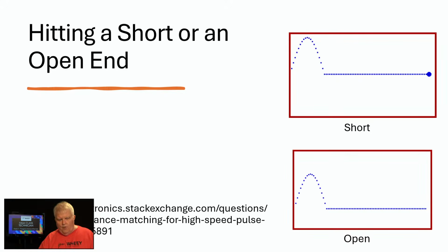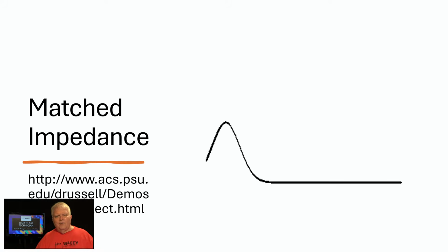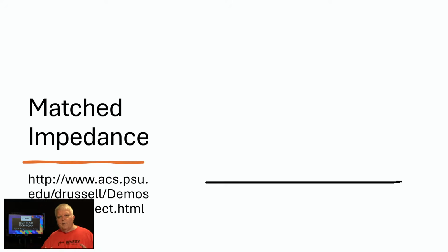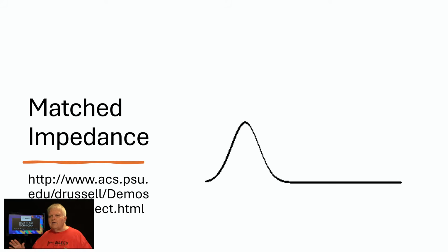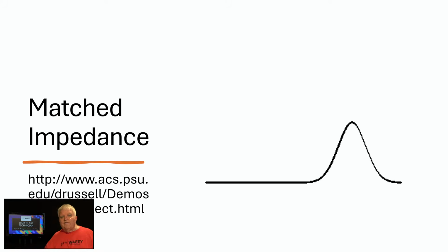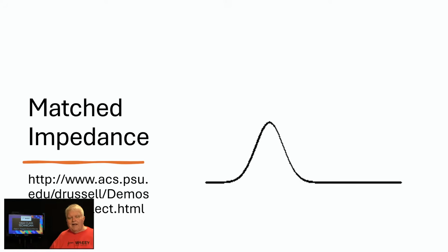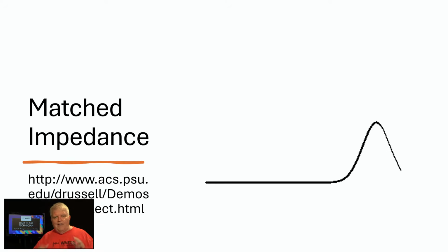What we're looking for, though, is this, where the energy leaves the transmitter, goes down the transmission line, is absorbed by the antenna and radiated out into space. And there's no reflected power. There's no rebound wave coming back from the antenna. That's what we would like to achieve, if at all possible.